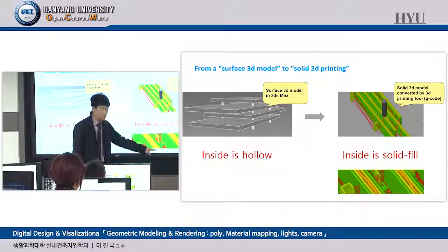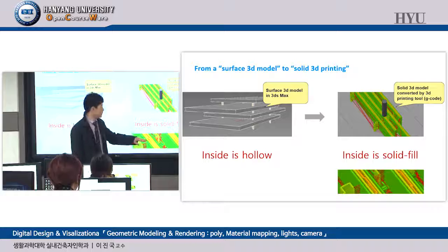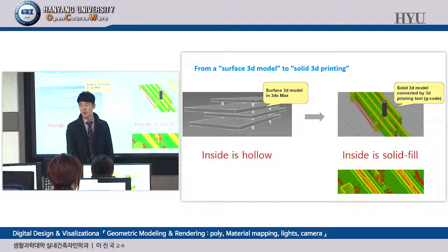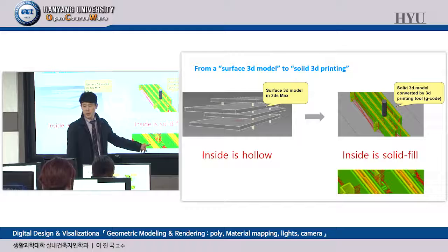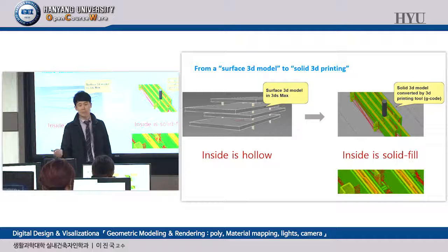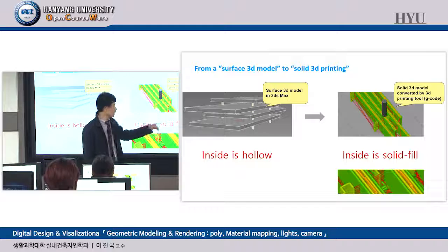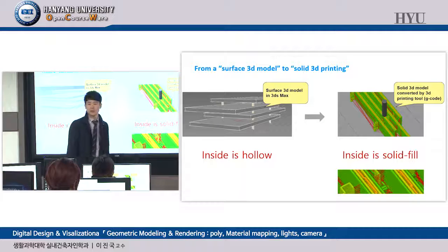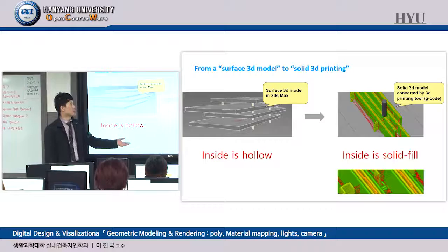Inside has autofill. Okay? Actually not 100%. If you fill the inside of the structure 100% with material, your product is too heavy, the printing time is too long, and the material cost is expensive. Okay? So 50%, 40%, you have the option. You can control it. So autofill inside is a feature we can take advantage of in this kind of tool.